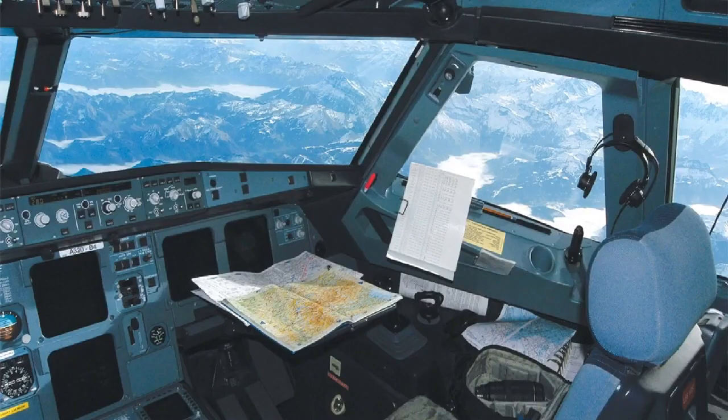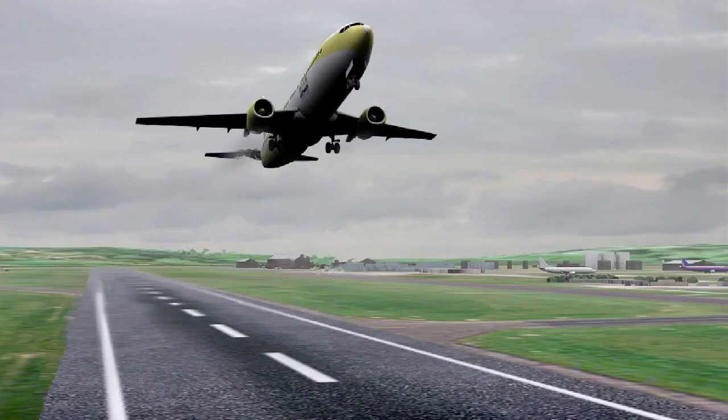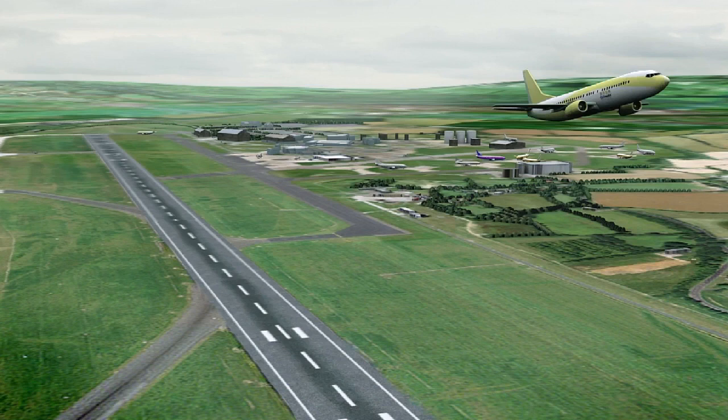The different levels of engine power are nominated by the following terms. Takeoff thrust. Maximum thrust available from the engine. This power setting is normally time limited. Go around thrust. This power setting can be the same as that for takeoff thrust, but it's normally a slightly lower value.